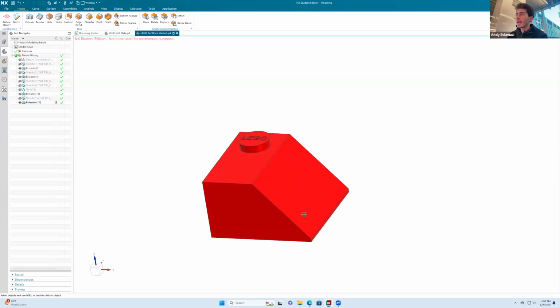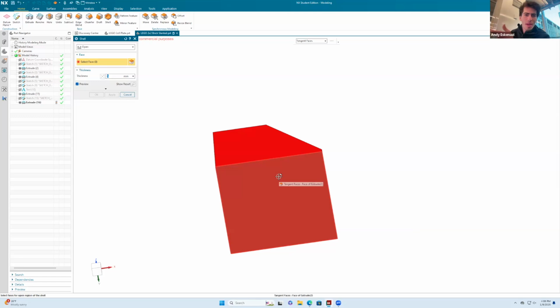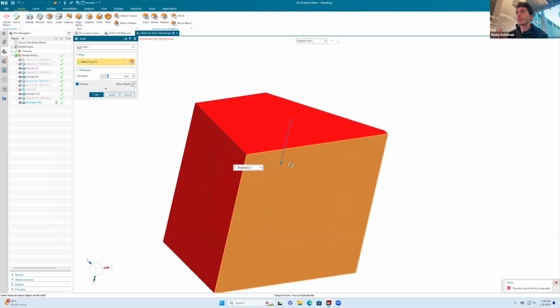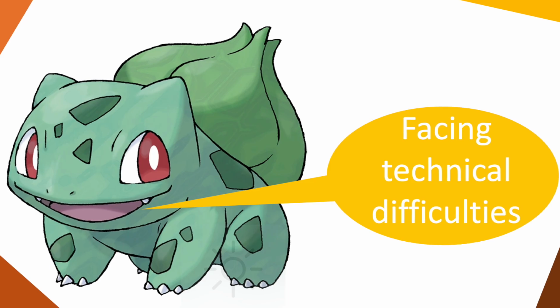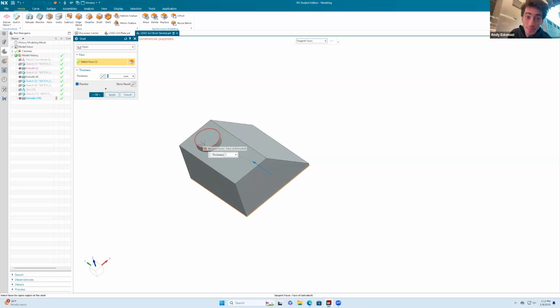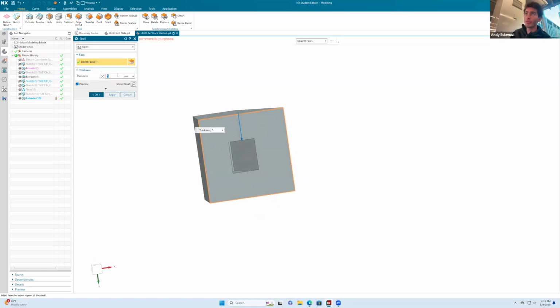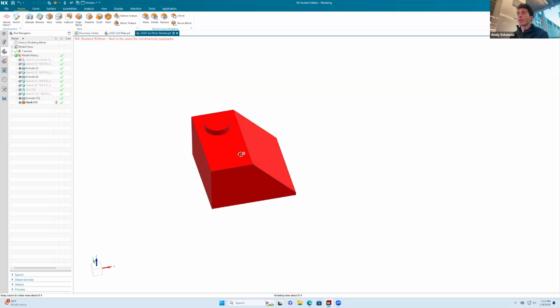The reality is that now I'm going to employ a different command that's called shell, which maybe I should have done in the first place too. But I can do shell thickness over here that when I give it 1.2, the reality is that that little Lego writing that I had in there was messing up with all of this stuff. But now here's the beauty of this command, right? That it takes us, this is exactly what the piece is supposed to look like. So I click here in OK, very good.